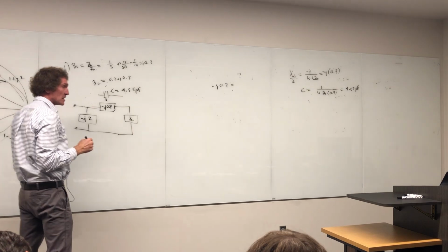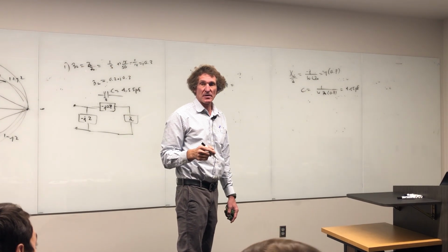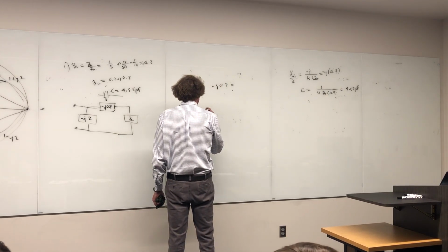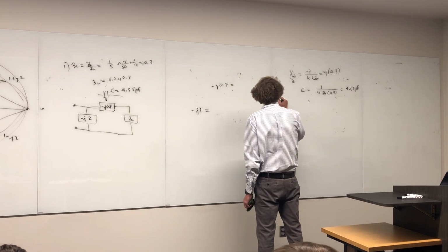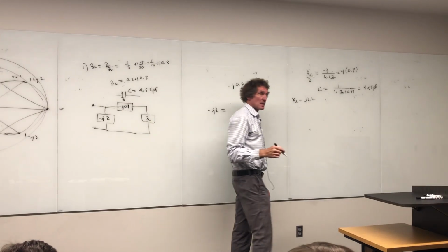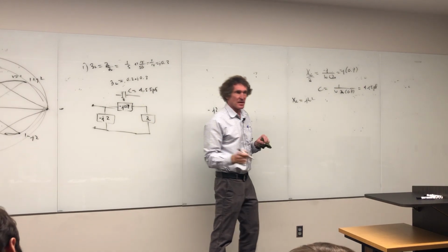What about this? That's admittance because it's in shunt or parallel, correct? So I have minus j2 equal to, well, what do we say? If we have an inductor, the inductor's impedance is equal to j omega L. If we normalize it, you're going to get sick of hearing this, but you'll remember it.